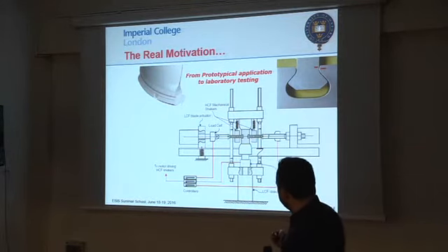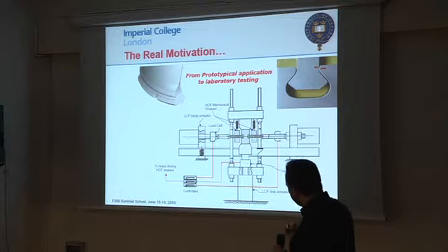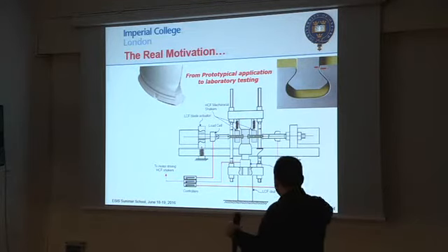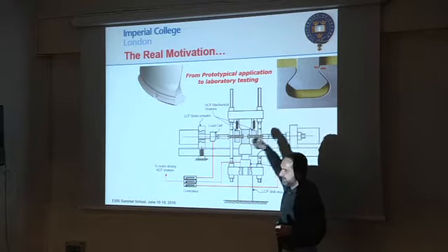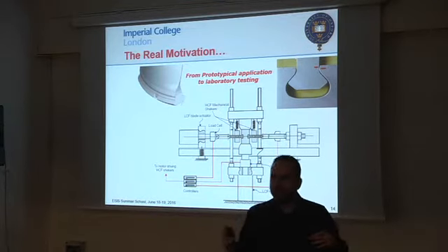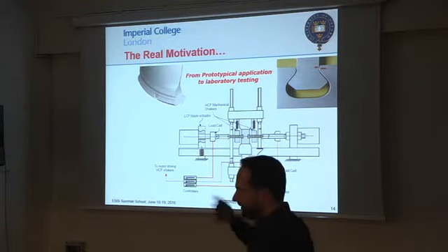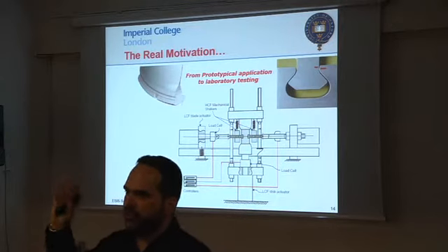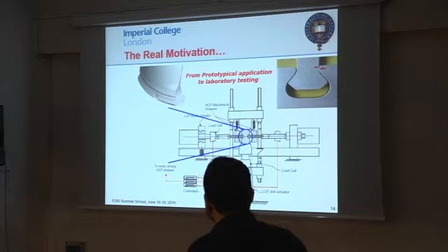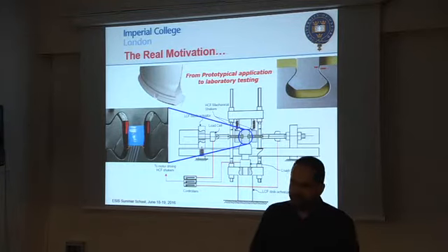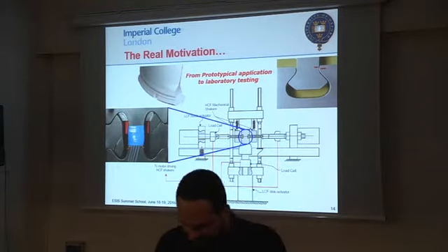They take a system which has got a bladed disc here, which is just a coupon. And this coupon has a dovetail, which is these inside there. And what you can do, you can apply the load, so you can take the specimen and pull it this way. You can pull the disc as well to replicate the centrifugal load that you have during flight. And then there are two shakers here, one there and one there, that can also show the oscillation on the blades as you fly. And when you do the test there, you can actually just try to replicate the cracks and failures that you have in those systems.